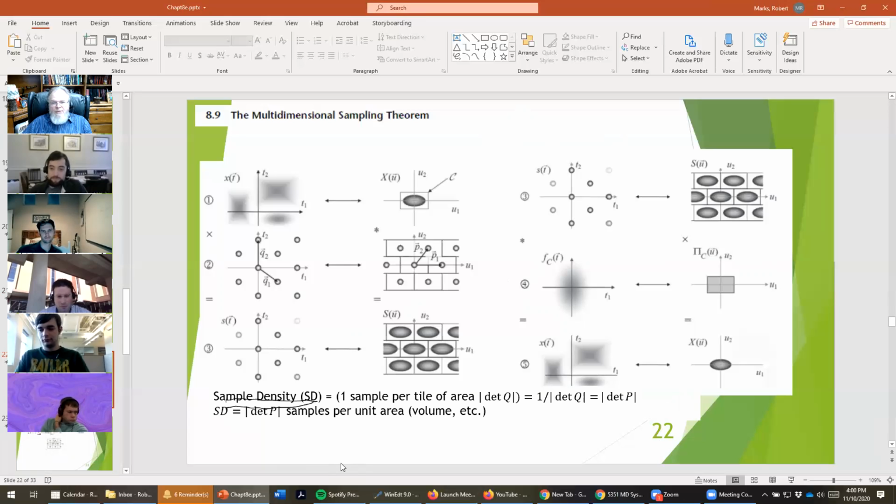And the sampling interval is equal to 1 over twice the bandwidth of the signal, if you remember that. That's the Nyquist rate. Do you recall that? We actually went through an example with the sinusoid where we said that the sampling rate had to be a little bit bigger than twice the bandwidth. Remember, with the sinusoid and the Dirac deltas canceling out in a weird sort of fashion. But let's just say for purposes of discussion that we sample at twice the bandwidth.